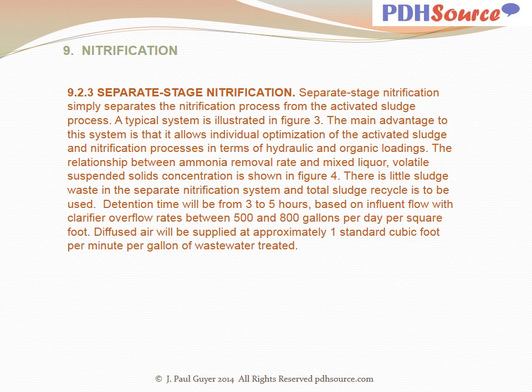Detention time will be from 3 to 5 hours based on influent flow with clarifier outflow rates between 500 and 800 gallons per day per square foot. Diffused air will be supplied at approximately 1 standard cubic foot per minute per gallon of wastewater treated.